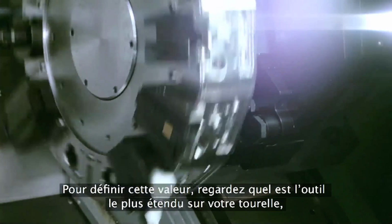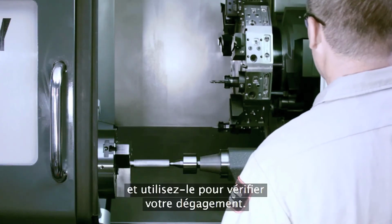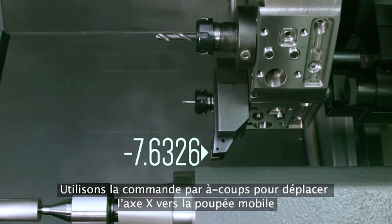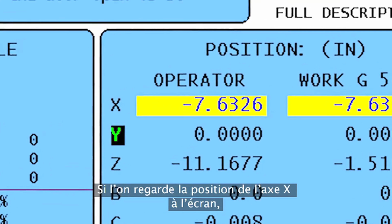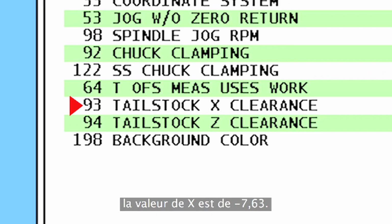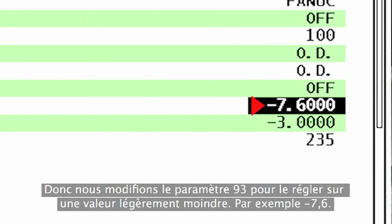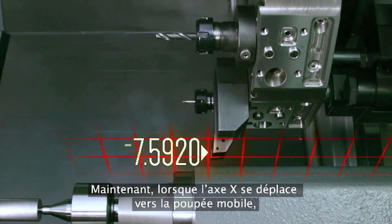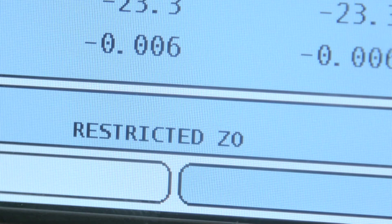So to set this value, find the most extended tool on your turret and use that to check your clearance. So we jog the x-axis down towards the tailstock until we find the clearance we're happy with. Looking at the x-axis position on the screen, the reading is X-7.63. So we'll change setting 93 to a slightly smaller value, like -7.6. Simple. Now, when x-axis motion moves toward the tailstock, it will halt just shy of -7.6 before the tool can crash.